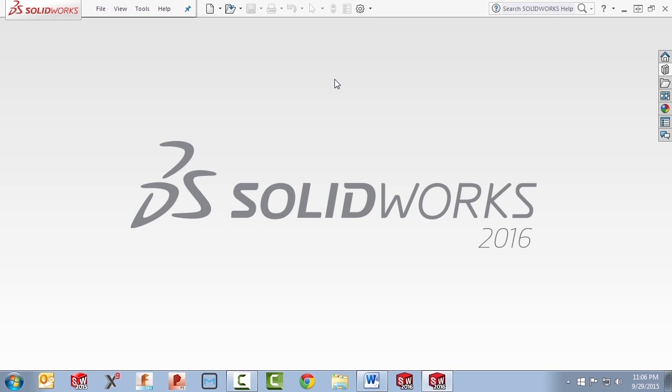What I want to focus on here when we first run SOLIDWORKS is how you can get access to creating new documents or opening existing documents. By default, your file section will be unpinned, so you'll have to use this right arrow to go ahead and show it or hide it. I like to keep this pinned open because it doesn't take up too much space and it gives us quick access to things like creating new documents or opening recent files.